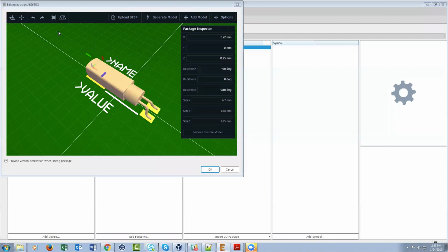You cannot do the whole 3D thing offline. So if you export a step file from Eagle, you're not going to be seeing the 3D models with it. You'll be seeing square boxes most probably, because all of our 3D conversion is going to be on the cloud. But you'll see that everything in 2D will be perfect.